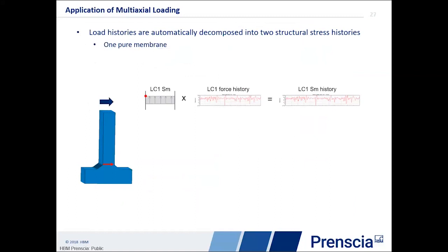Again, these structural stresses can be either from the shells or from the coarse solid models, but what they represent is a definition of a linearized stress for a particular loading mode. And the two loading modes that we're focusing on are membrane and bending, because those are the dominant loading modes for these cracks that we're looking at.